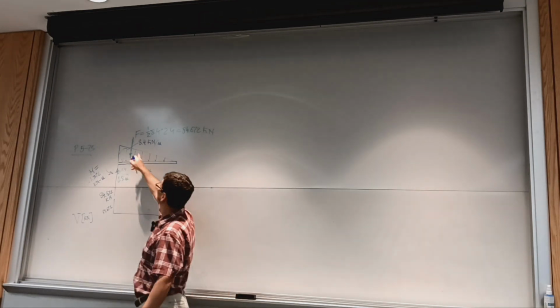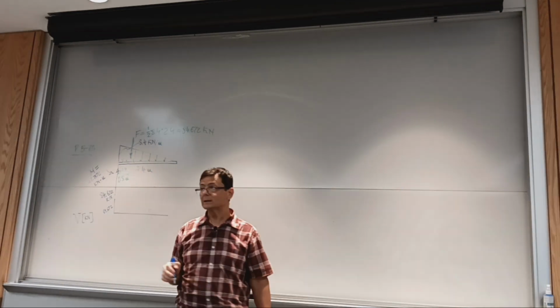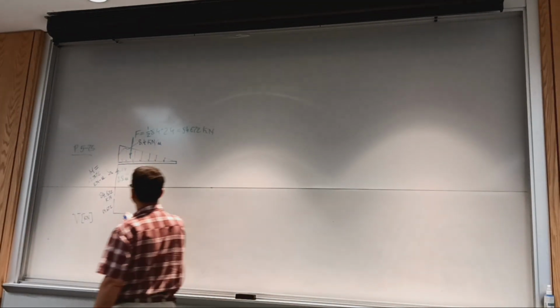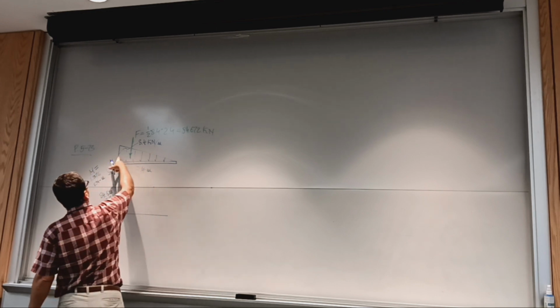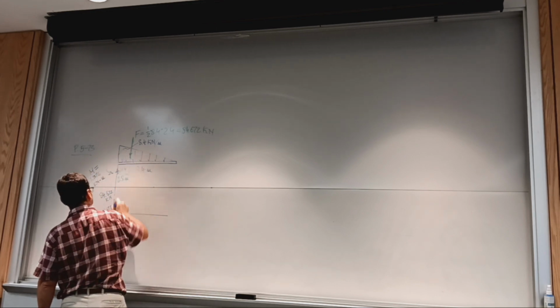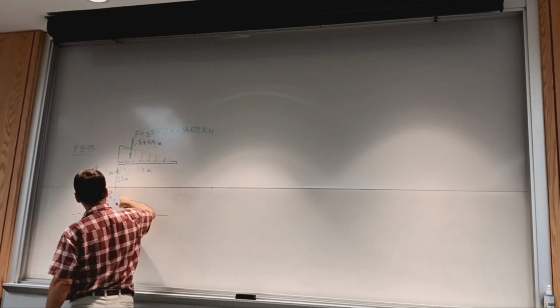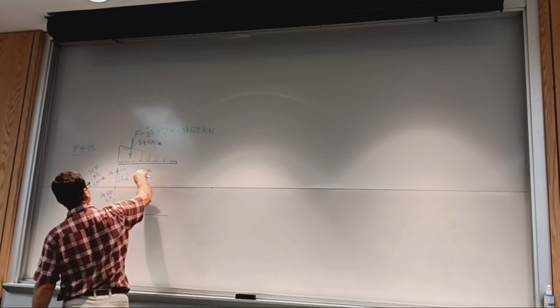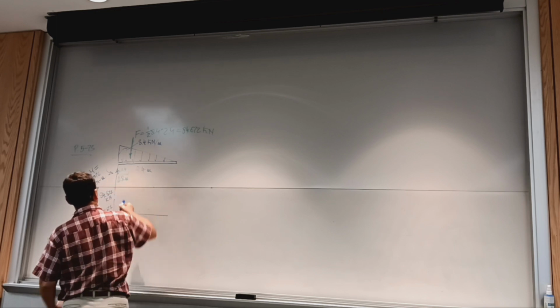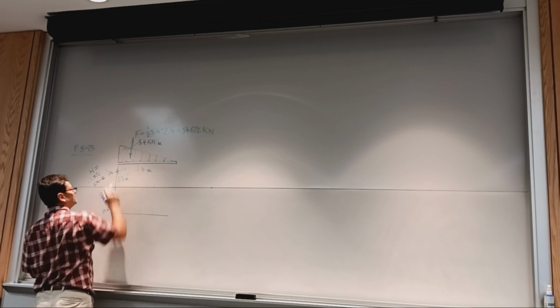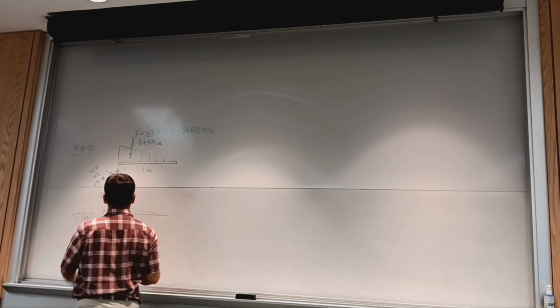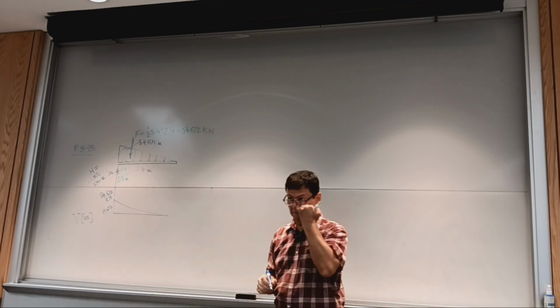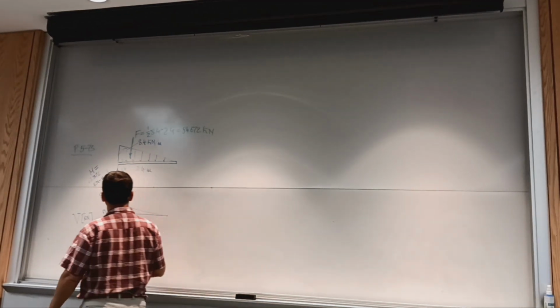Because the load is linear, this is going to be parabolic, going to zero from the maximum value. The slope of the parabola is negative and diminishes. So it goes from a maximum, which is this piece, to zero. This is going to be the shear diagram.